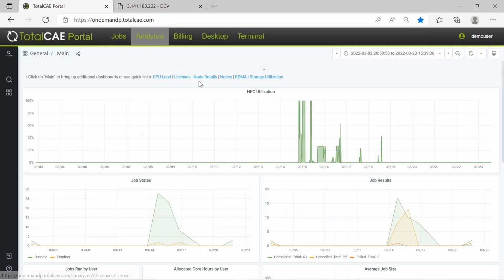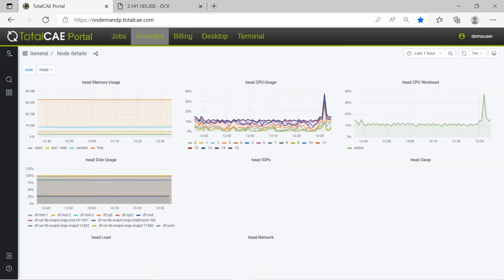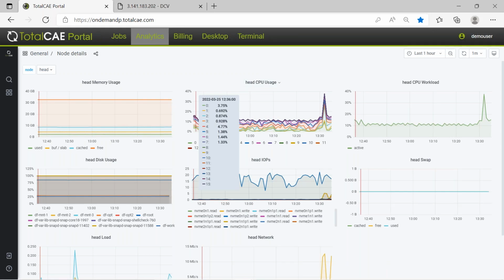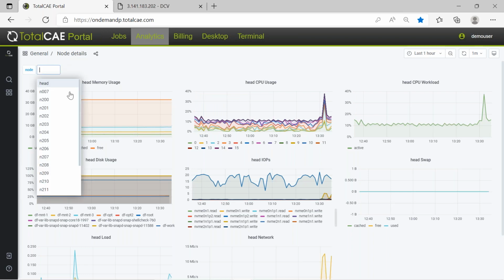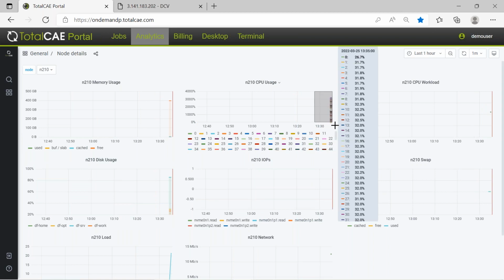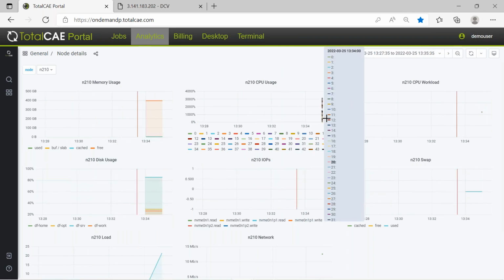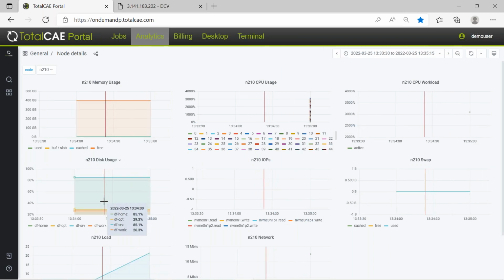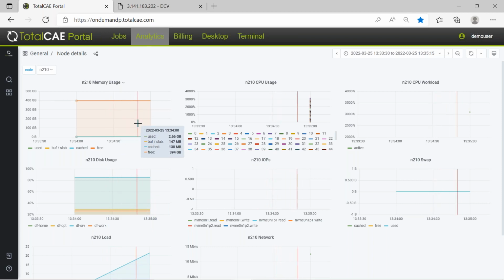And then one thing that's kind of handy: if you look at these jobs that are running, once they power off, if your job didn't run, you may want to know what happened. Did I run out of memory? Once the node turns off, it's hard to go back and see what happened. But with this integrated analytics, we can go back and dial right into what was happening at that time. Even though the node is turned off, I could go back and say, okay, did it run out of memory? No, I had plenty of memory. Or maybe it did run out of memory. Then you'll go back and choose a different instance type that has more memory for your job, or maybe you reduce the mesh, or whatever you need to do to get the memory footprint down.